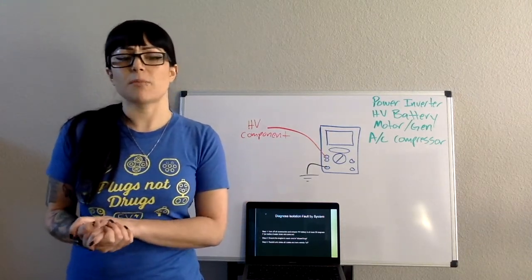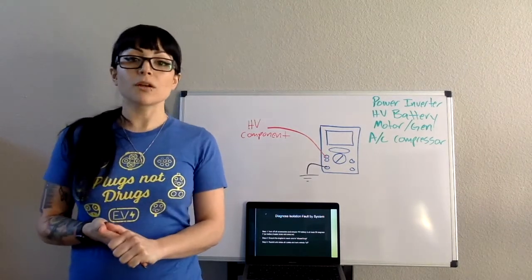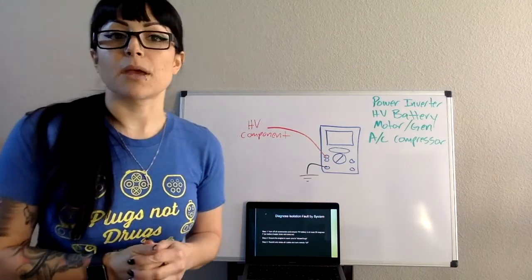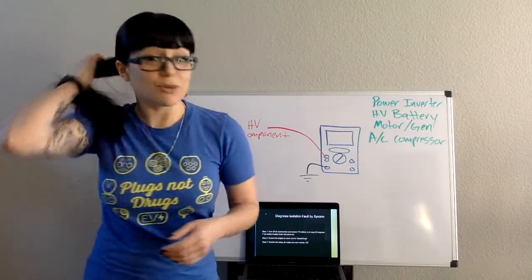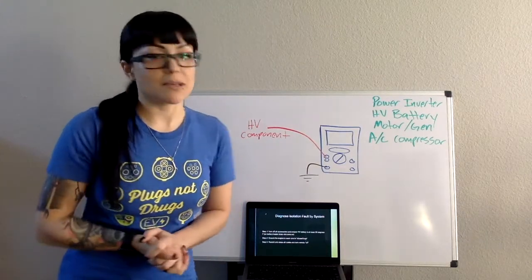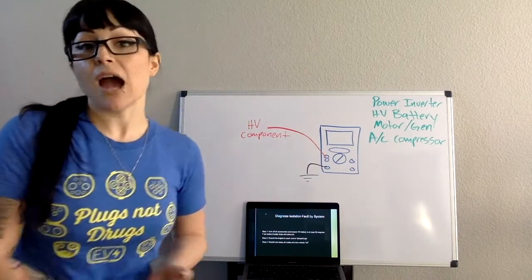So you want to make sure that the battery is at least warm enough, for those of you who live in colder areas or work in colder areas. Down here in SoCal, it doesn't really become a problem. We do have cold days out here in the Inland Empire, so neither here nor there. Make sure your battery is up to temperature. Once your battery is up to temperature, make sure the engine is warm if it's a hybrid vehicle.